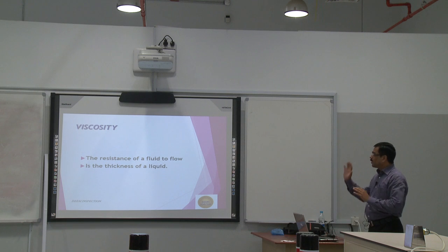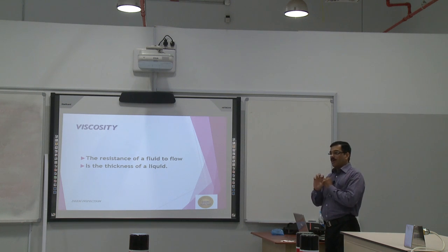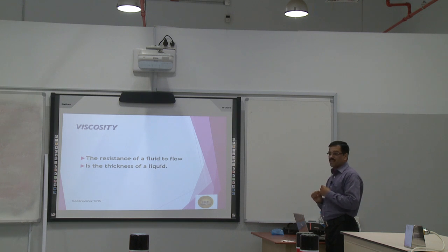We are talking about penetrant on a surface. The basic theory is that penetrant testing can be used only on non-porous material, with defects open to the surface. These are some basic characteristics of our penetrant. It works on the basic principle of capillary action.